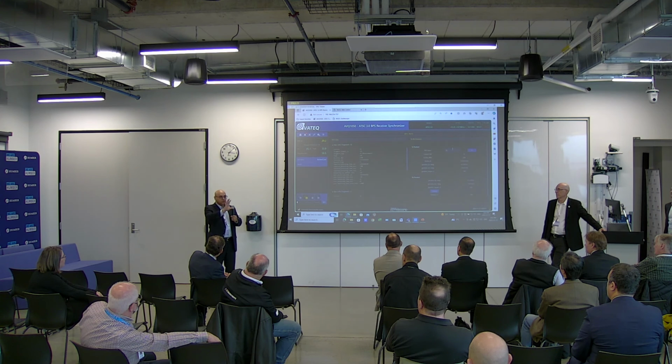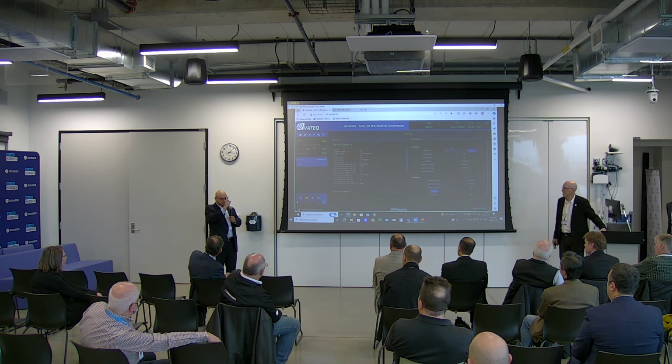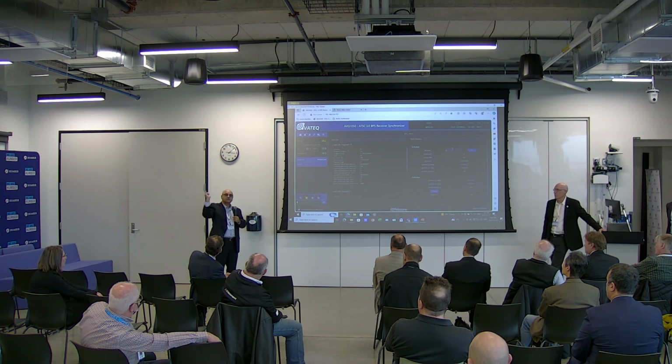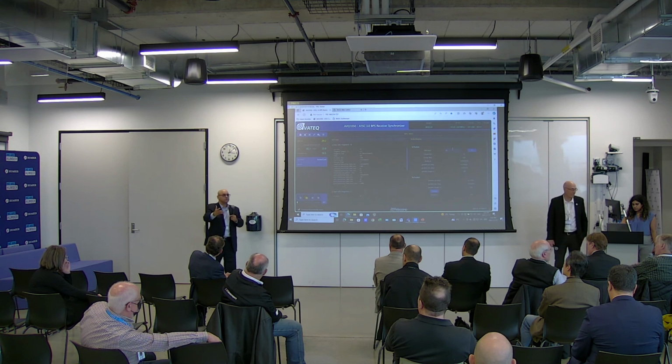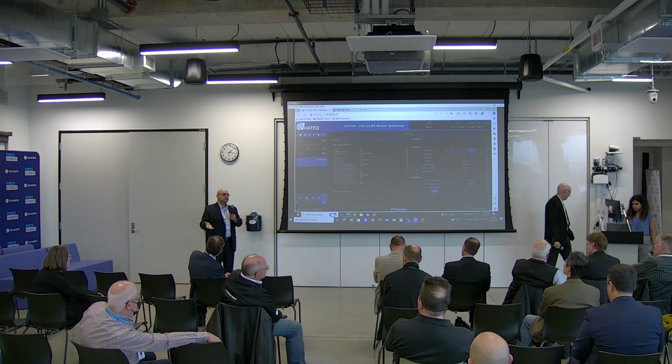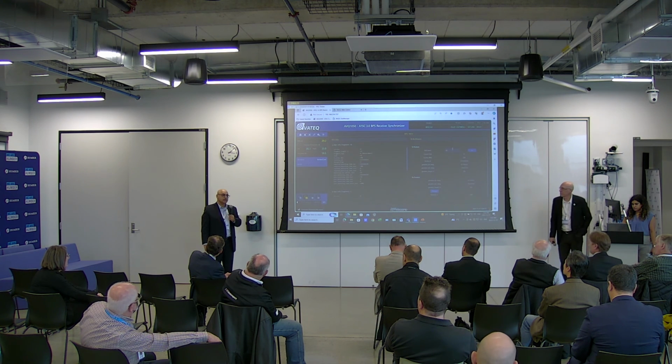You can have one configuration with two cesium clocks. You can have one GPS coming in with the beamforming antennas and anti-spoofing. You could have STL in there, different Iridium constellation time, and then you can have dark fiber backup, and they can also have a fiber, because of the symmetry that is measured using GPS. It's very accurate. They say that the fiber could get like 10 nanoseconds. The overall thing they call the EPRTC, the budget is less than 10 nanoseconds.